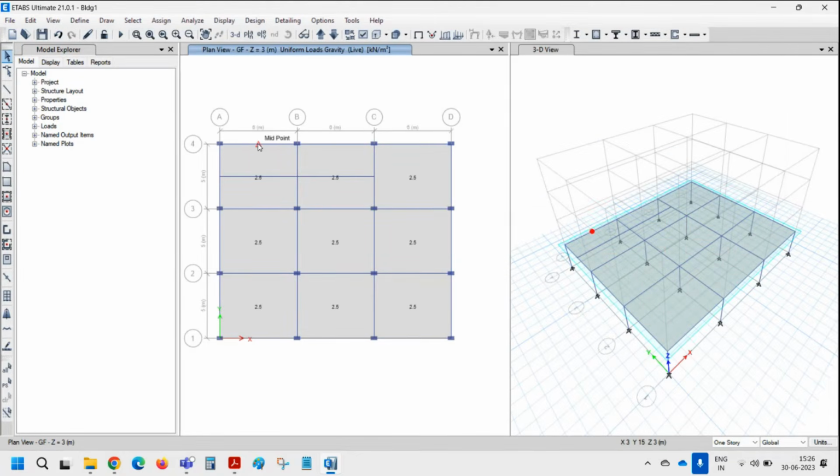Let's complete the loads. Masonry wall loads typically are assigned as loads. Then we can select objects, the beam objects, quickly. Let's assume again the same option you can use and select all the beams. Let's assume only the periphery beams are having the masonry wall loads, interiors are not. Then how to do it? You can use this like this.